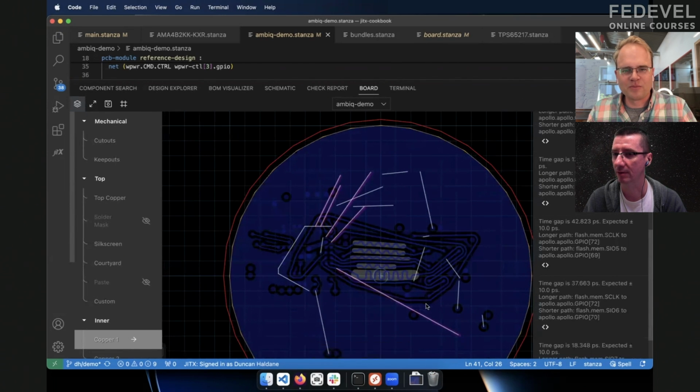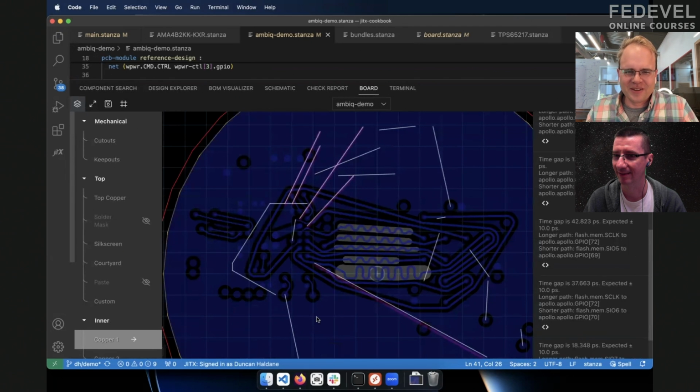And I bet you could route this a bit better than I did, but this is what it looks like. And this works. This can be a really size efficient way to do length matching, because you can get slight variations to make up time along a route. So we're testing this now. I had a DDR demo that I wasn't able to show because it uses some proprietary data, but then we got the OpenRex design to show the same concept.